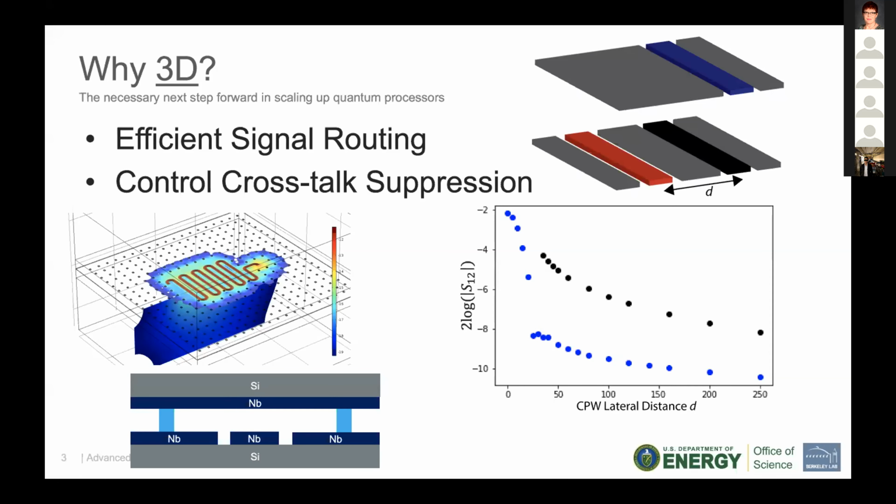And so this means that you can pack your elements denser and closer together without worrying too much about the crosstalk between them, if you design this Faraday cage appropriately. And on the right-hand side, we simulated another scenario where we try to understand the crosstalk between the waveguides, the control wires that carry your quantum signals and the coupling and the signals and the single photons.